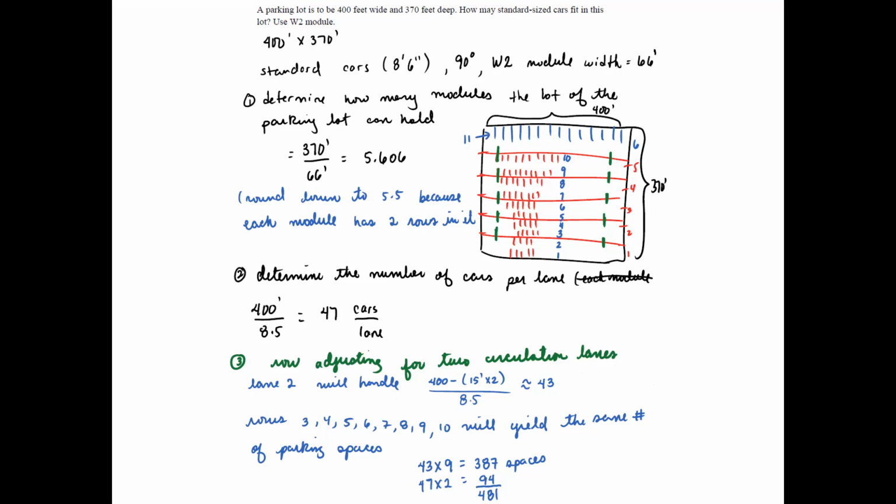If your goal is to accommodate as many cars as possible and you have limited space, then most likely you're going to end up with an angled parking design in which you limit the flow to just one direction for most of the lanes. That is what you typically see if you go to HEB and these stores that are typically full most of the time. You will have angled parking spaces with flow in only one direction.